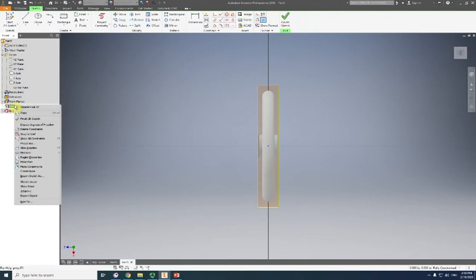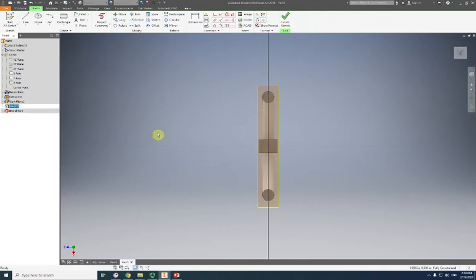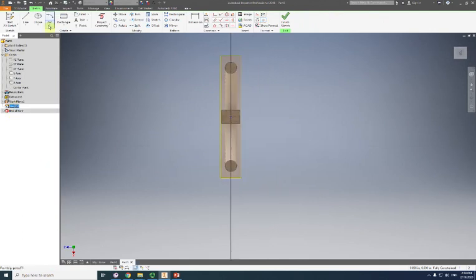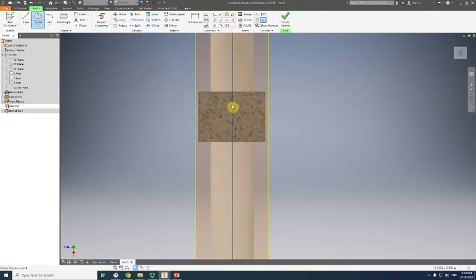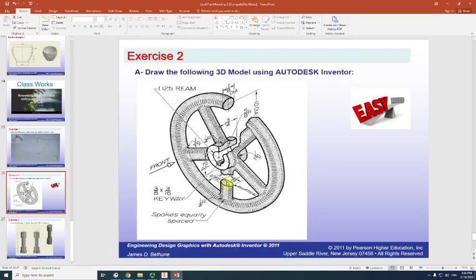Now we can sketch on this work plane. Same step. Right click, slice graphic. Now we want to draw an ellipse at the center of the file. Okay, this is an axis and this is an axis. Now go back to the drawing. How much this length? It's 1 and 1 over 8. Half of it, how much? Yes, half of the 1 and 1 over 8.